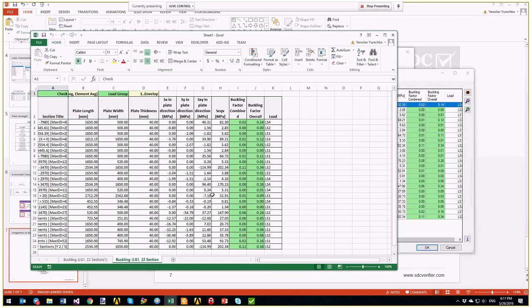Because what I've noticed is that if you have a plate welded on top of a joint of I-beams, and you do the extracted models, then when you're defining the connections between the plate and the beams, you get problems with overlapping boundary conditions because it's going to one beam and to the other beam, but they're both connecting the same node, and you have some radius on the connections. I don't know if you guys have talked to them about it at all. It's something I brought up in the last meeting.